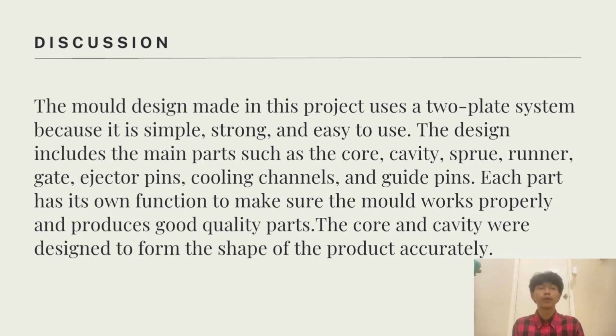Okay, now we move to discussion. The mold design made in this project uses a two-plate system because it is simple, strong, and easy to use. The design includes the main parts such as the core, cavity, sprue, runner, gate, ejector pin, cooling channels, and guide pins.